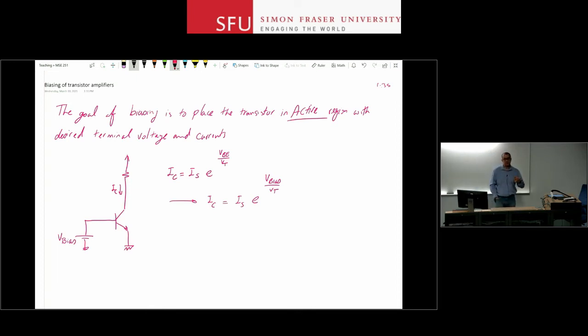More current means more heat. Therefore, you will get more current again. It's positive feedback. It's reinforcing itself. So you produce a little bit of higher temperature, then more current, then higher temperature, then more current, then higher temperature, and eventually you lose the device. If your power supply is ideal and can provide the current that is needed for that. Sometimes the power supply is limited in the amount of power that it can provide. But generally, it is a really, really bad way of designing the biasing.